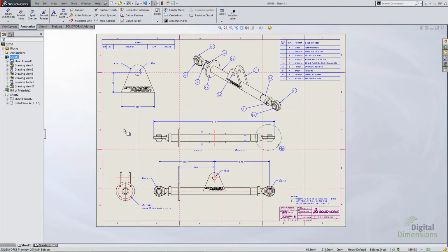The big thing here is obviously you're going to have to make sure these zone lines match up to your actual definition in your template. To modify your zone lines, you have to edit your template. So it's important to note that in 2015, if you want the zone functionality to work, there's a pretty good chance you'll have to modify the template, edit your zone lines, and save the template again.